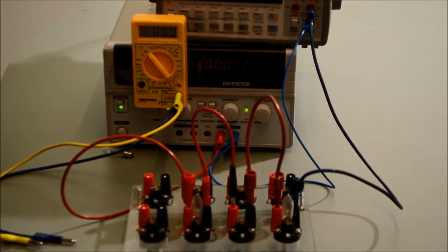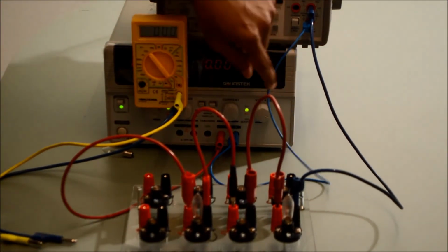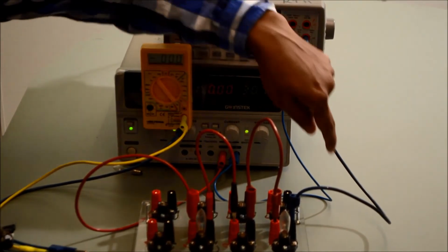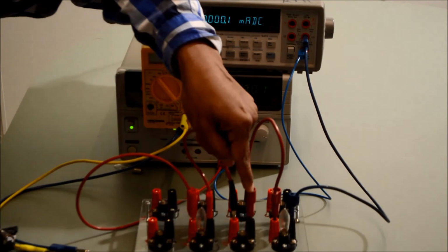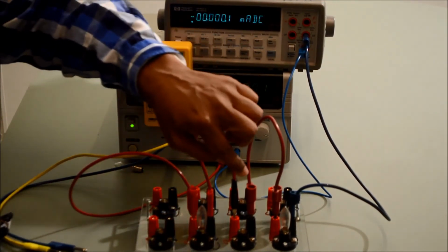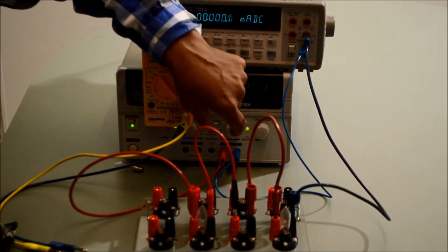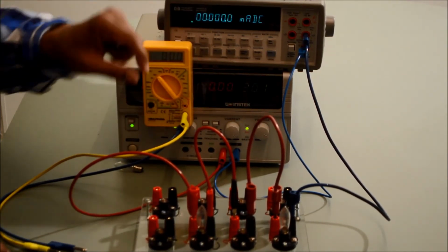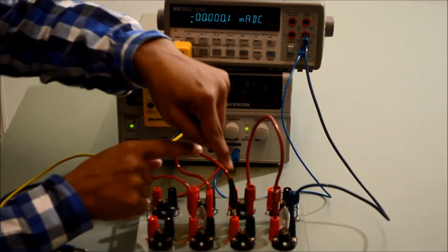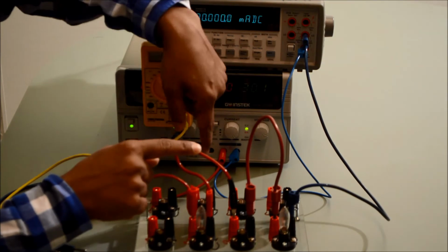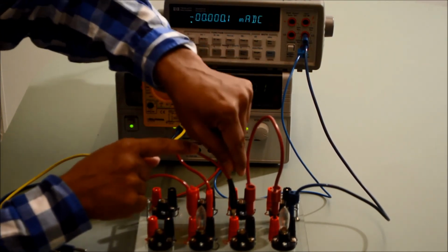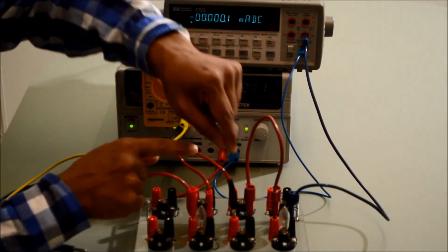Why? Actually, because we see that this positive pole is connected through the cable here until this point, and the negative pole is connected through this bulb until this point. So basically the plus and minus pole of the battery is here, because electrically the whole cable can be considered as one point. So we could say that the plus and minus poles are here. So this 30 volt is here.